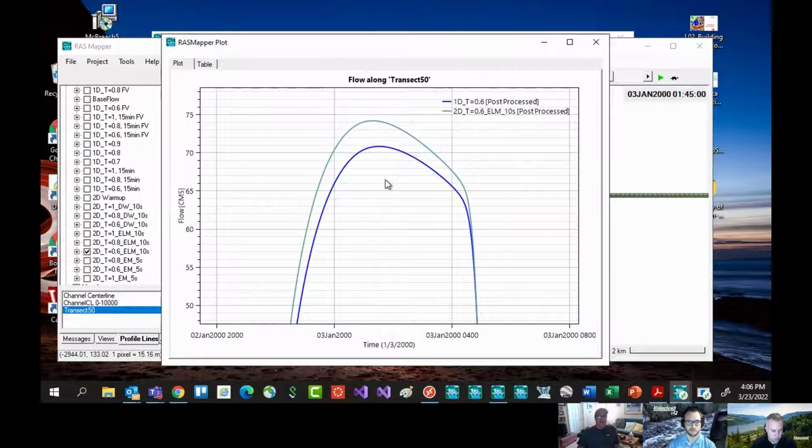Okay, and that tracking, unfortunately, has to do things like track back faces, but it also has to estimate velocities in the middle of cells. And so there's some numerical averaging happening. And because of that kind of stuff, you can get some numerical diffusion of that velocity term, that inertia term.